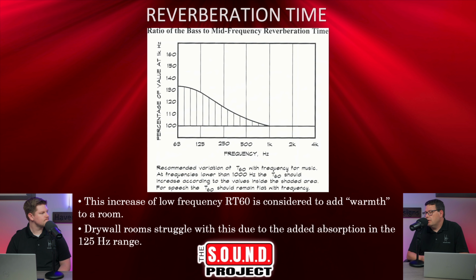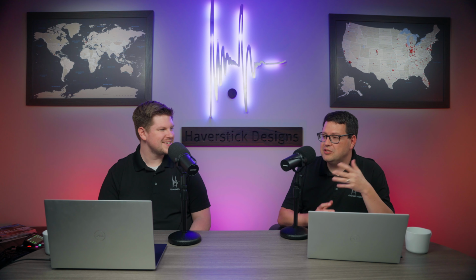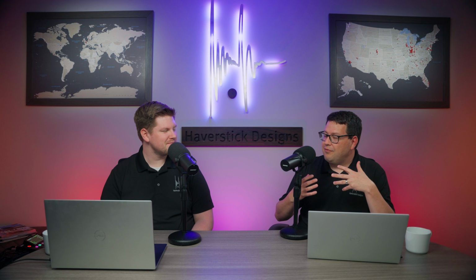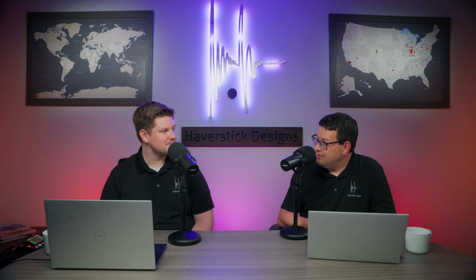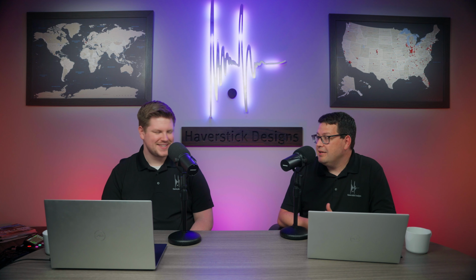We did a job once for Christ Fellowship Church down in Florida. It's a precast concrete building with concrete floors with thin carpet on it, and then a steel ceiling. When we did the model of that room at 125 hertz, the reverb time simulated to be about 6.5 seconds, which is insane. Imagine filling up the room with that energy and having to wait a full 6.5 seconds for it to die out. That's excessive. Normally it's not that long, but it can get up there.